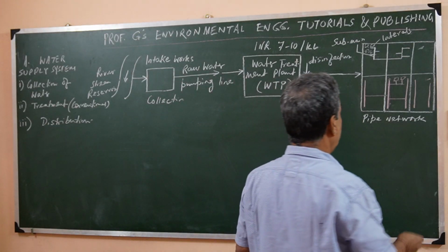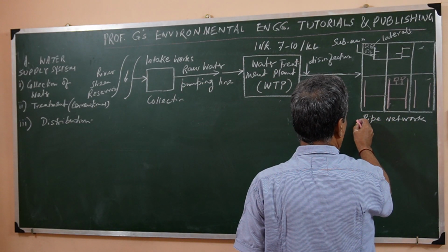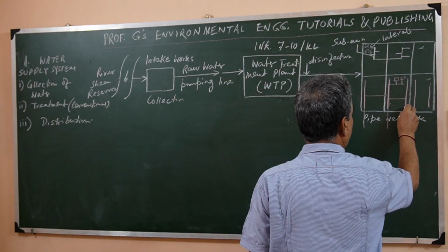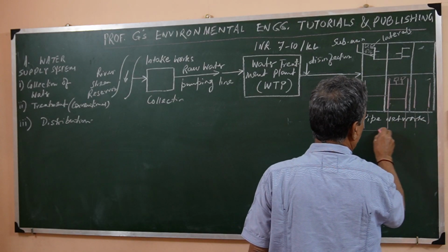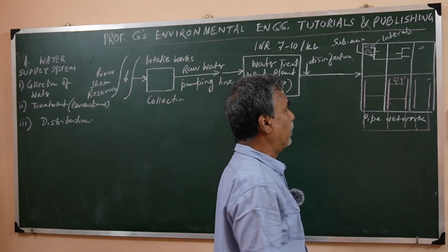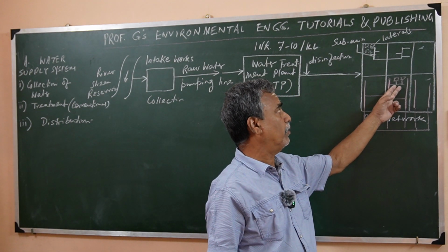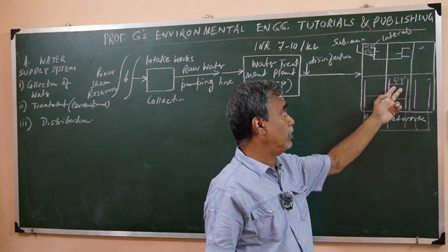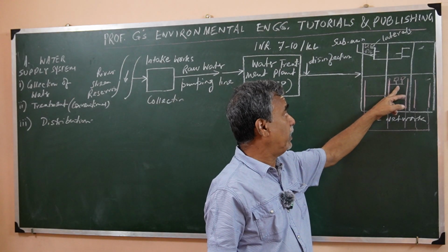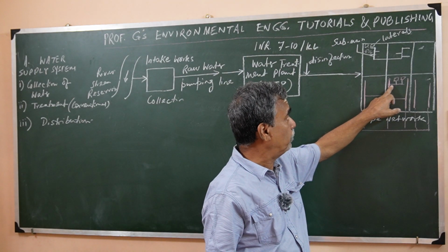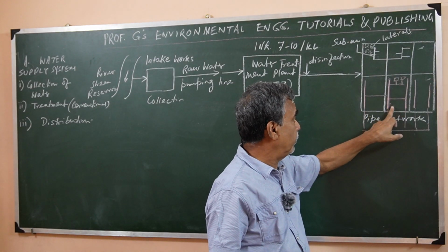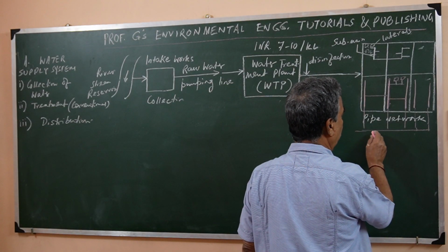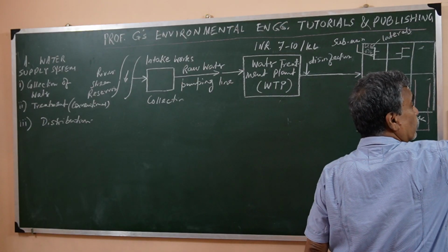So from this what we do actually, suppose all these are connected this way. Here also the laterals will be there, which will be collecting from the different units, like buildings, institutional buildings or residential units. Then it will be carried through the submain; if we call it lateral, this is submain, then this is main, and afterwards this finally will come to the intercepting sewers.